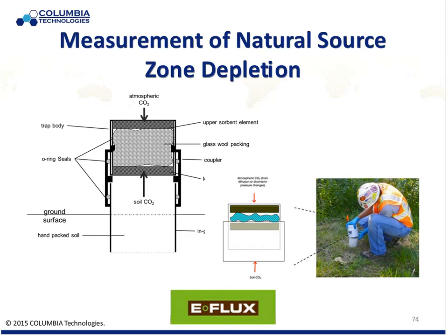eFlux has a tool out there. Again, that is generated out of Colorado State research work. And so you can look at what my degradation rates are coming up through the formation and in the source zone compared to my uncontaminated zones. And if you've got source depletion rates naturally that exceed those you can achieve with your mechanical systems, then you're probably not spending the money wisely on mechanical systems.